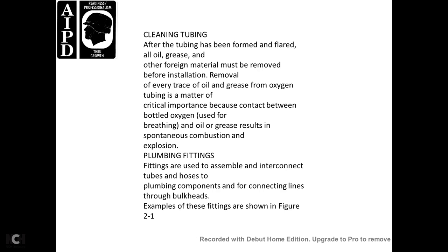Cleaning tube. After the tube has been formed or flared, all oil and grease or other foreign material must be removed before installing. Remove every trace of oil and grease from oxygen tubing. This is of critical importance because contact between oil and grease and the bottled oxygen used for breathing can result in spontaneous combustion and explosion.